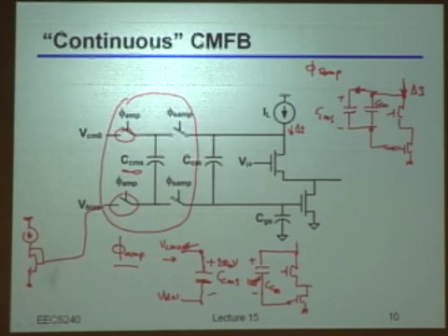So does this capacitor with switches at the edges tell you anything? Have you ever heard about switched capacitor resistors in the past? Who heard about that? Okay, yeah, a few people. So that's what I implemented here. I used switched capacitor technology to implement a kind of resistor. A resistor is transferring charge continuously, because there is a continuous flow of current over there. Here, I'm transferring charge from one spot to another in packets, in small quantities of charge.